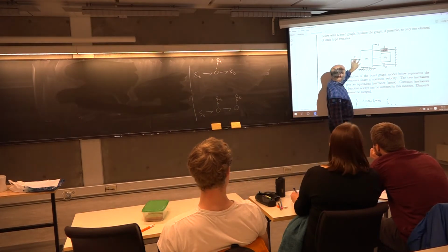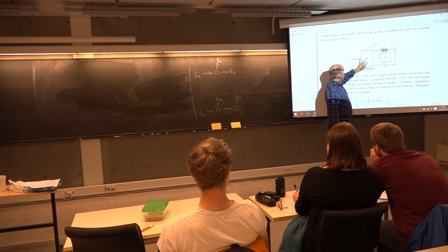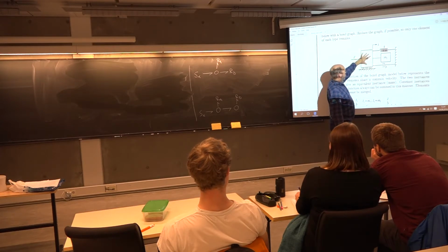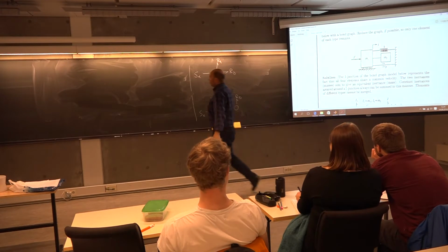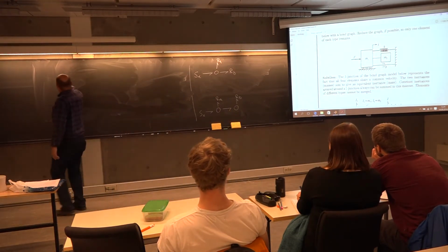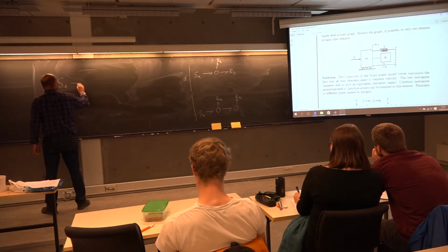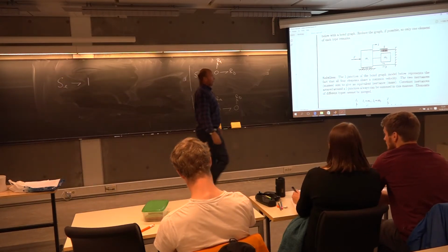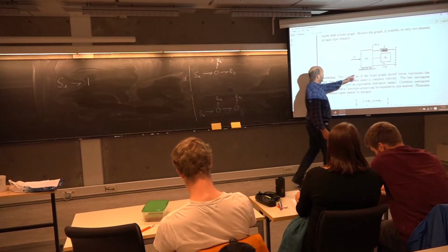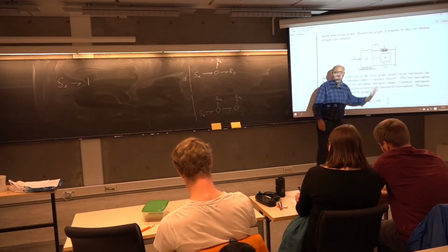Start with the force here and the first mass that it hits. This mass, it's a big lump, is moving with a distinct velocity. So to describe this motion, I need a one junction. One junction, that was the common flow, the common motion. So I will start with an effort source hitting a one junction. This one junction has some mass attached to it, mass number 1.